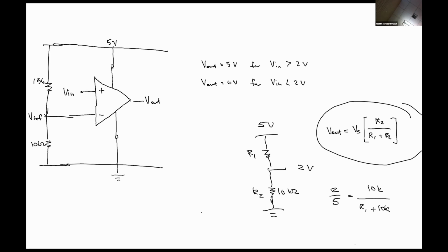our reference voltage will be set to 2 volts and we won't have to come up with some 2 volt source, because 2 volts isn't something that's used regularly, right? You could get 1.5 volts from a battery. 3.3 volts is a common output from a microprocessor, as is 5 volts. But 2 volts is kind of an odd duck. But we don't have to bring in a whole different power supply, we can actually use simple resistor networks to create any bias condition we would want, as long as that bias voltage is between the power supply voltages.